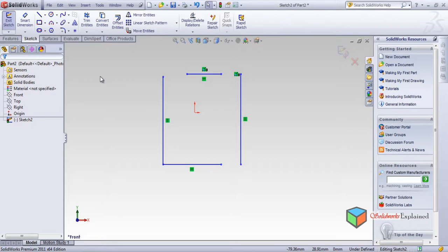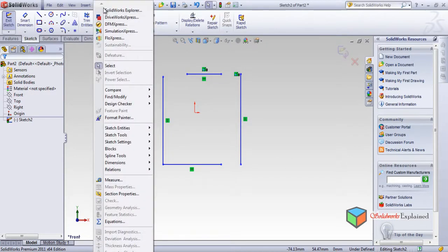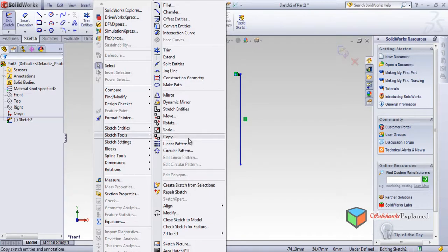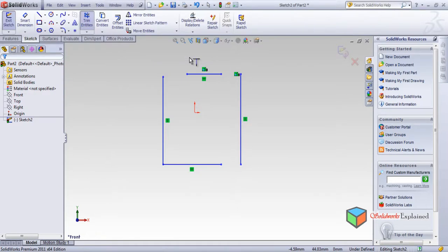In my earlier section, I was making a spline and the two things were not joining, and we were not able to join them. Here I will do it differently. Go to Tools, Sketch Tools, and then the second option, Extend. Click on Extend. Look, it will show an orange line. Left click, done. The extend work is done.